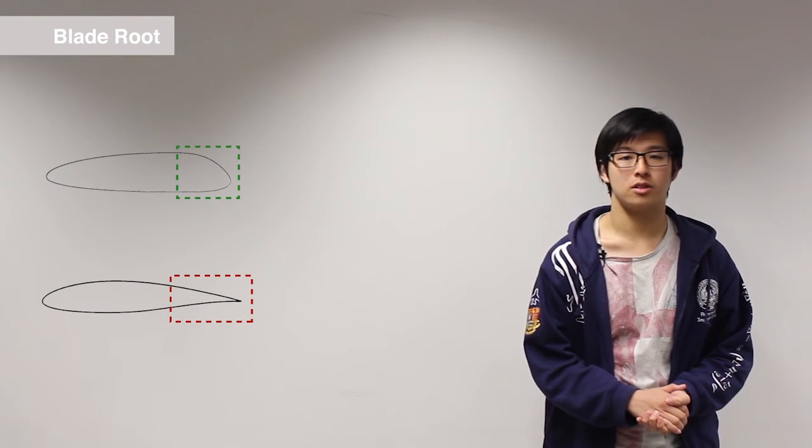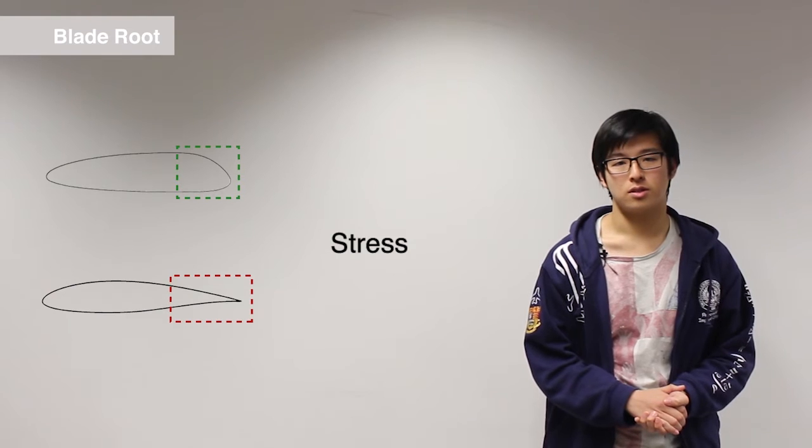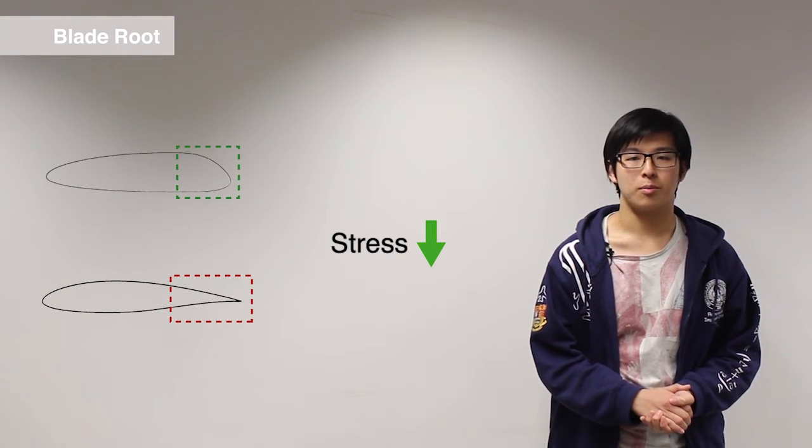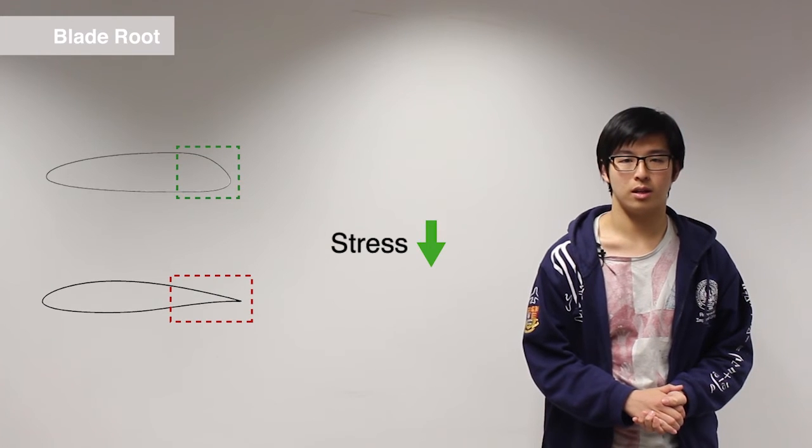We used a modified SG6040 airfoil section to connect the blades to the hub. The trailing edge of the airfoil was modified as a blunt edge. This brings us 3 advantages. Firstly, this avoids the high stress intensity in a thin trailing edge. Secondly, the flow separation occurs further downstream than the regular elliptical cross-section, and this reduces the drag.